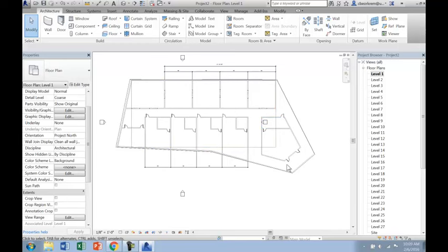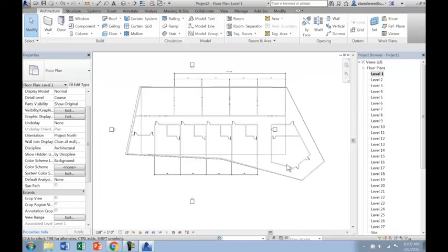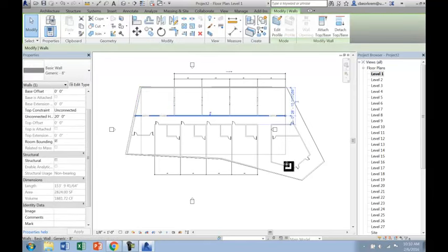But we're also going through and defining a series of smaller room definitions to align with different parts of this. So the first thing I want to go through and show you is just ways in which you can actually diagram now that you've defined each of the different definitions. So one thing to look at is the wall type that we've been using, just this generic 8-inch wall type.